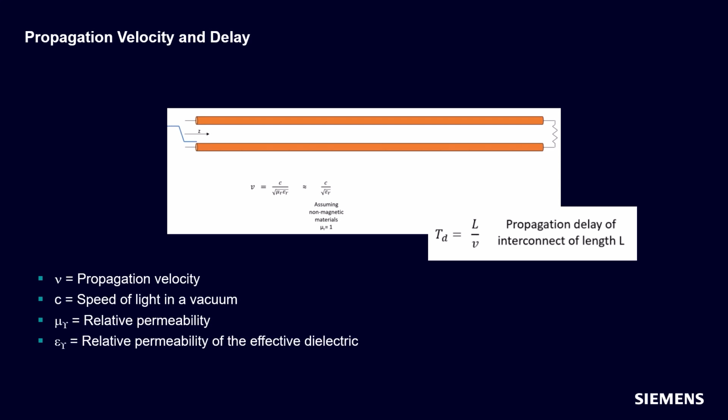A larger dielectric constant directly causes a reduction in the signal's propagation velocity. Therefore, a higher dielectric constant results in a slower signal velocity and, consequently, a greater delay over a given length. This experiment demonstrates why the selection of PCB dielectric materials is a critical consideration in high-speed design.